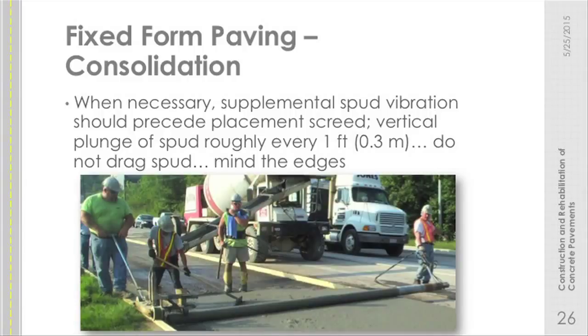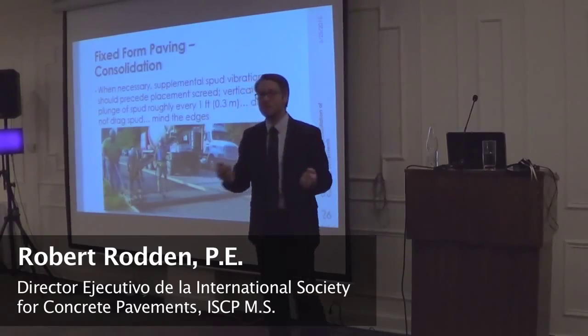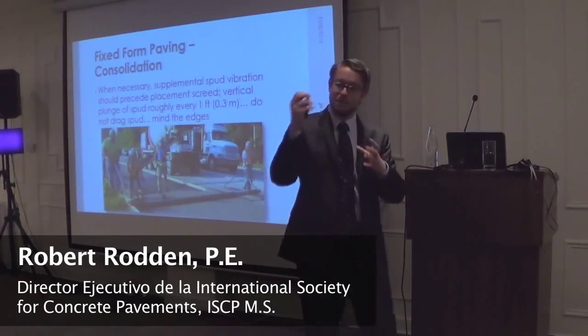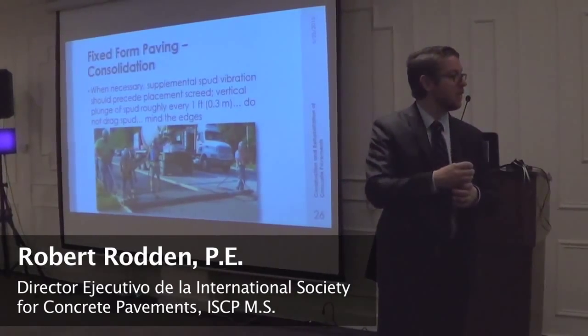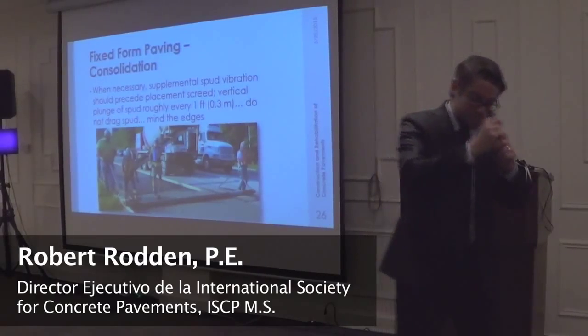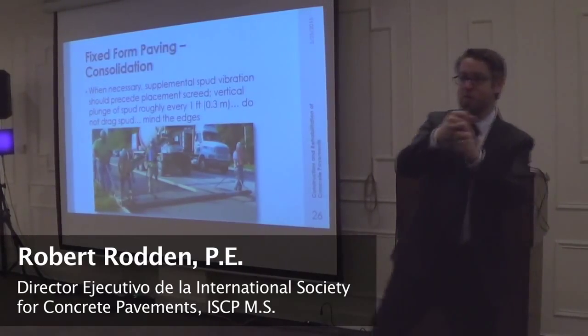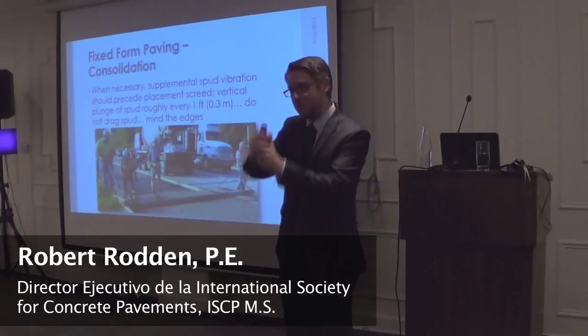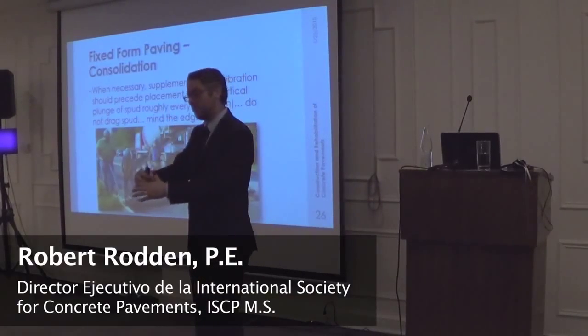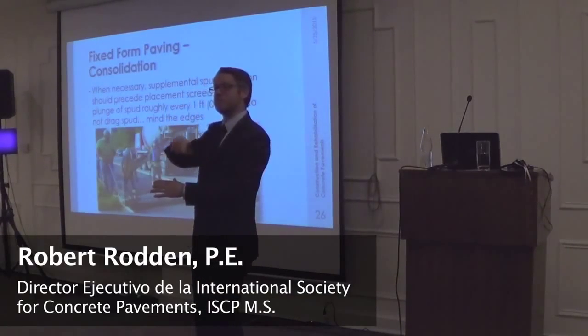Consolidation, if necessary, if it becomes so thick, greater than about 20 centimeters, that the screed itself can't do the consolidation. This gentleman here has a backpack on which powers this spud vibrator. So it's just like the vibrators on the slip form equipment, except it's one single vibrator. So they will dip that in one location, move over, dip that in the next location, and always do it vertically so they have a constant zone of influence.